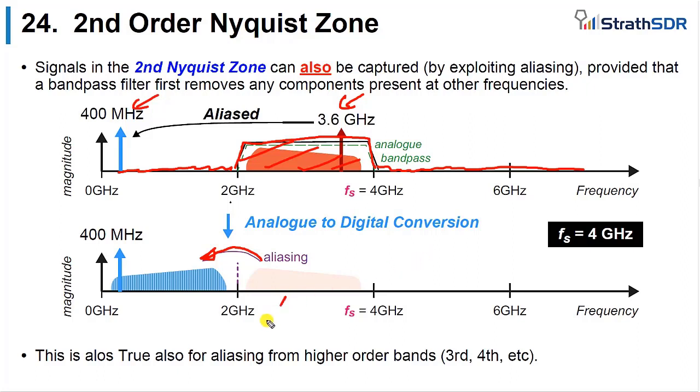Now you might be thinking, oh, the spectrum has flipped and the relative position of signals has moved, but that's not a difficult issue to deal with. We can easily flip that spectrum round with just some very simple processing. And of course, it's up to you to remember or to note where your signals have gone. So if you are interested in a particular band here, great. After aliasing, where's that going to be?